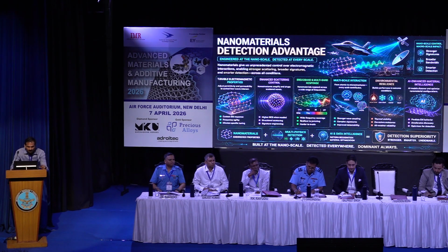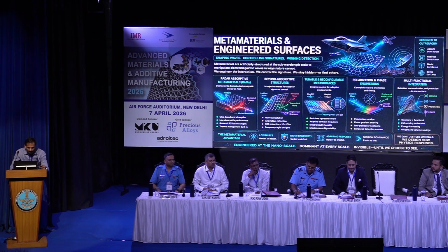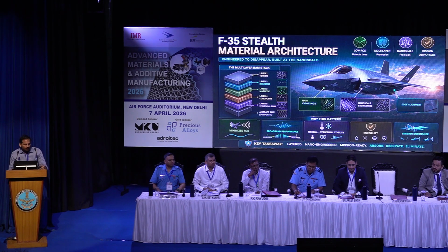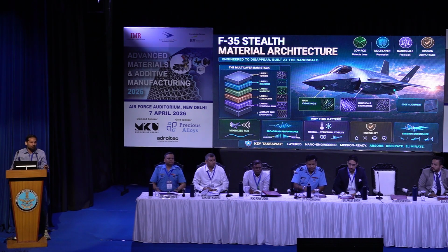Now the materials, I will skip because of time. Here, how are these stealth layers prepared? We have many layers. First is the protective layer, which protects against corrosion and other things. Then we have a top-coated dielectric layer which can absorb. This dielectric is not a normal dielectric, it is a nanodielectric. I have included some results. This is not a normal dielectric, where ceramic materials are included in a polymer matrix to create a dielectric. That is a nanodielectric.